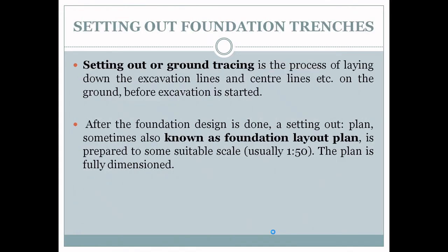Next, setting out foundation trenches. Setting out foundation trenches means marking the excavation line and center line on the ground before excavation is started. After the foundation design is done, a setting out plan, sometimes also known as a foundation layout plan, is prepared at a suitable scale.